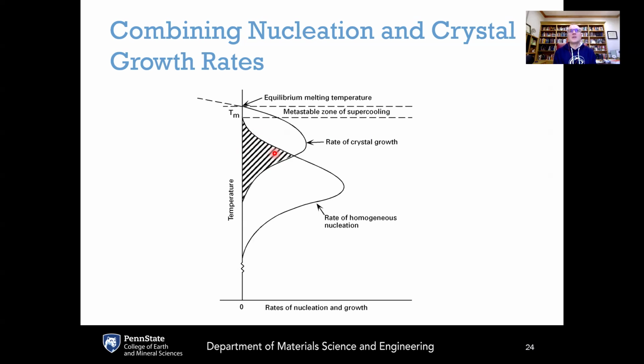The problem is that you don't have independent control over the nucleation and crystal growth processes if you are in this overlap regime, because both processes are happening at the same time. If you want to control these processes independently, then you want to be in a region first where you can nucleate and control the population of nuclei that you grow, and then heat the system up to the region where the crystals can grow from those nuclei.